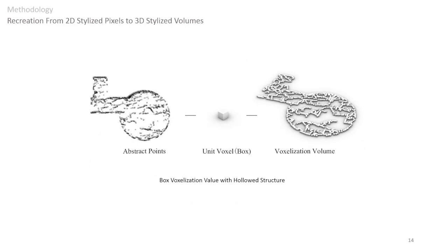To convert the 3D lattice into a form geometry, the basic elements of the voxel modeling are then placed on the filtered points for generating the voxelization structure. The adjustment of the grayscale value is then visualized as a folding density that controls the contribution of the solid and the void area. The original style image also becomes the interior structure basis rather than a plain pattern on the surface.